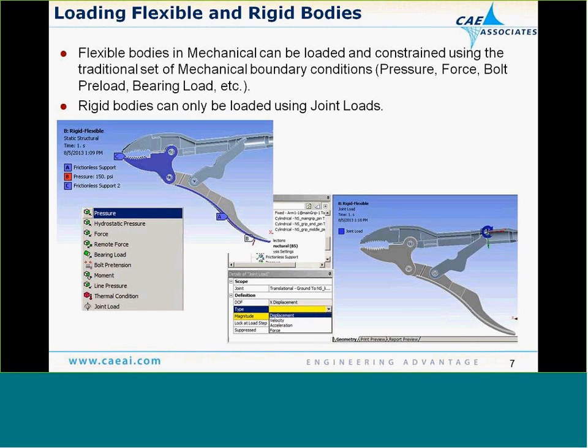If it happens to be a dynamic analysis, whether it is an implicit transient analysis, or if all the bodies happen to be rigid and we're using the rigid kinematics tool, we can put on loads as displacement, force, as well as velocity and acceleration.